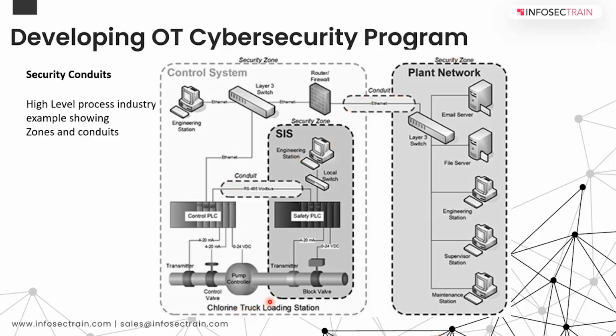So earlier, sometime back, I was talking about a safety system, which is kind of air gapped, right? This is the safety system that I was talking about. It's called a safety instrumented system. This is a safety PLC. The safety PLC takes some critical decisions, and if you see, it is not connected via Ethernet, or it is not in the same network. It is RS485 Modbus serial communication.